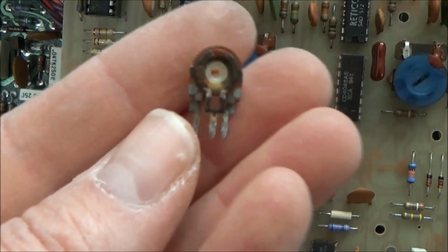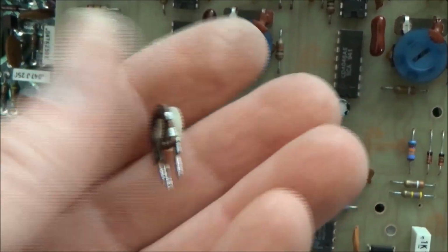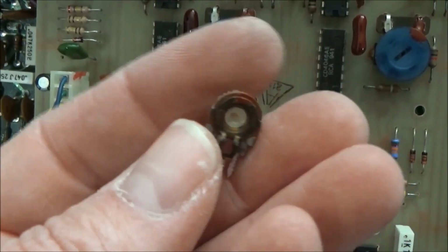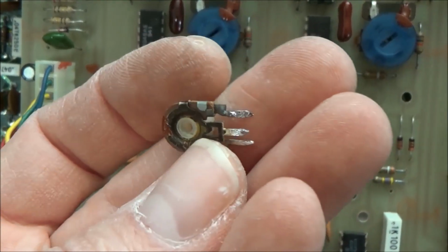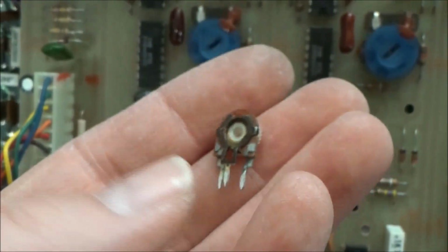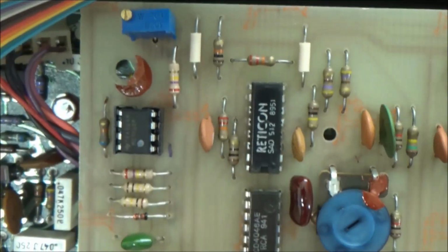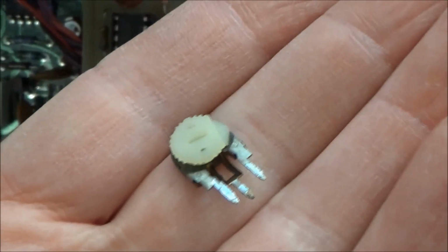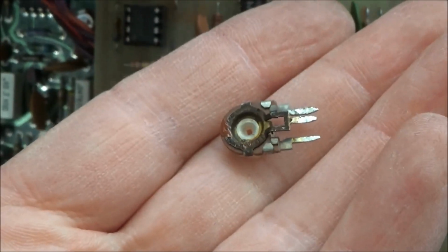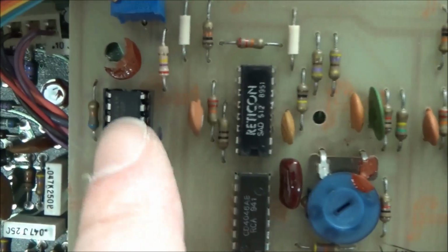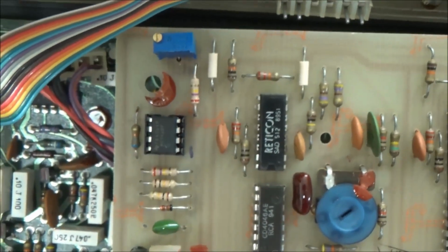The trimmer that was there looked like garbage. I mean, it's this open frame type of trimmer, and if I had realized that was there ahead of the op amp, that would have been the first thing I suspected after the op amp and the diode. So I changed that with a nice multi-turn trimmer, and now let's check out the output.